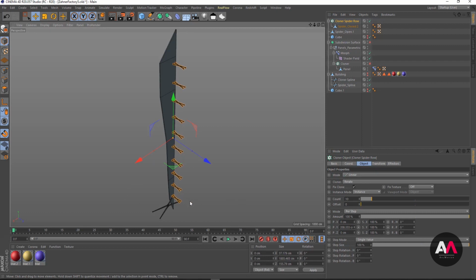So to prevent this from happening, I'm temporarily going to add values here. I'm going to increase the distance to 416.667 to halve the number of the spiders, but it's temporary. At the end, when everything is okay, I'm just going to divide this value through 2 to get the final distance that we wanted. So now the spiders are in the correct position.